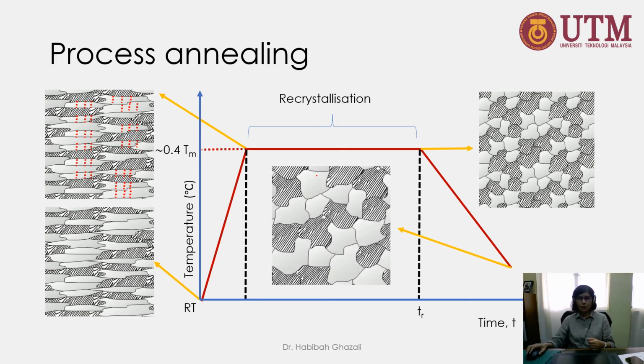Depending on the rate of cooling, we can stop them from growing bigger or we can let them grow bigger. Bigger microstructure means that the material will be more ductile. Smaller microstructure means that the material will have higher strength. So that depends on what we want. If we want it to stop at a very small microstructure, we can fasten the cooling rate. So that's what it is.